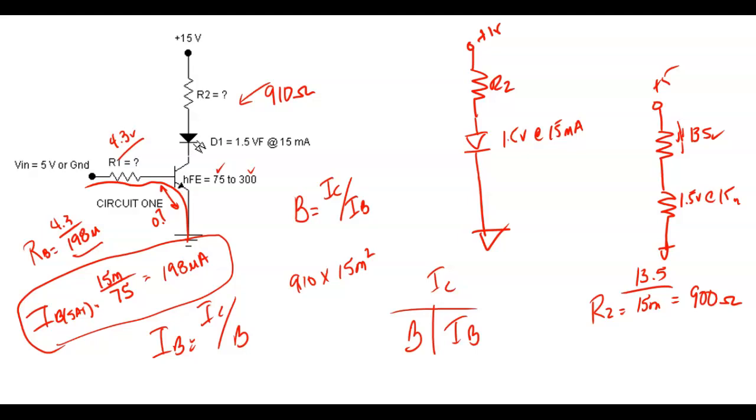21.71 kilo ohms? Yeah, you've got to get that right. In electronics, you just can't say 21.7, right? Of course, what we're going to do here, we're going to round down, but we've got to assure saturation, so to the next standard value. So what would we use there? Was that 20K?